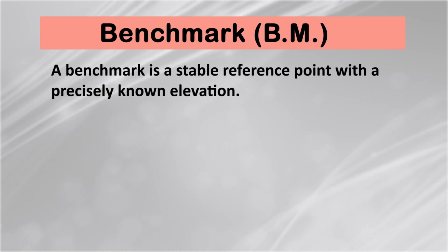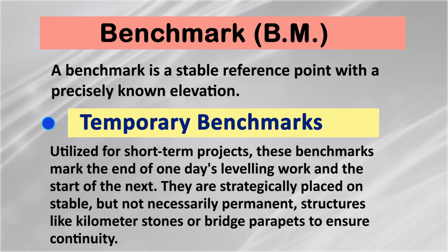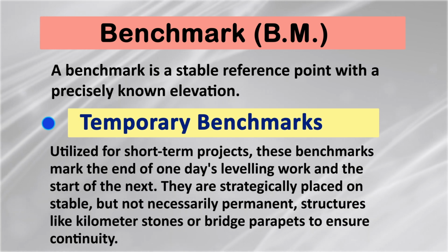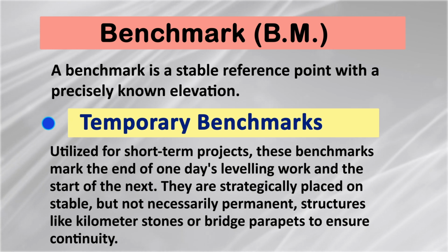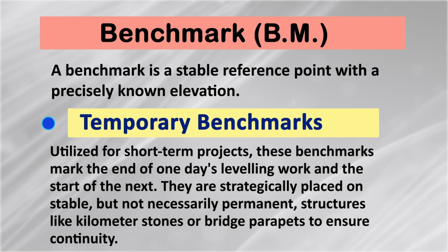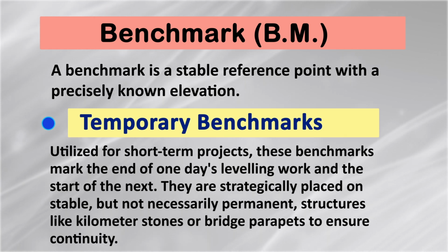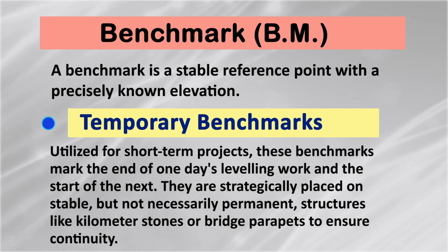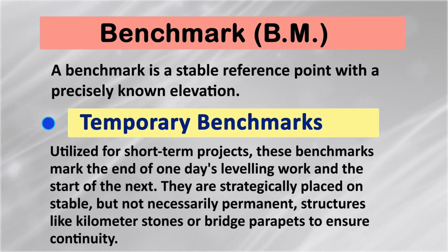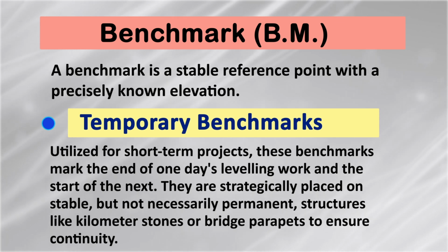And last one is temporary benchmarks. These are utilized for short term projects. These benchmarks mark the end of the day's leveling work and the start of the next. They are strategically placed on stable but not necessarily permanent structures like kilometer stones or bridge parapets to ensure continuity.